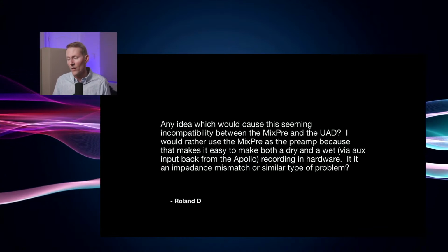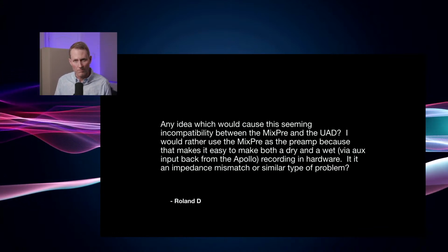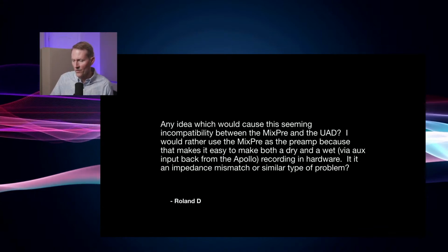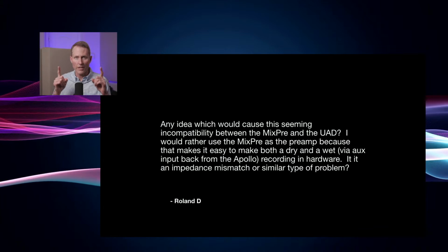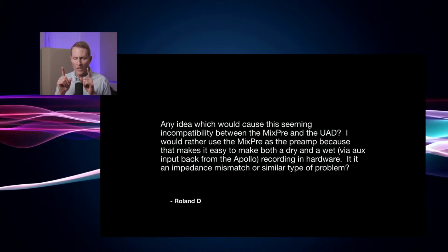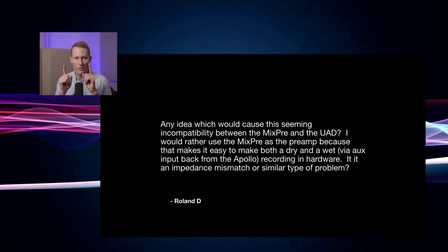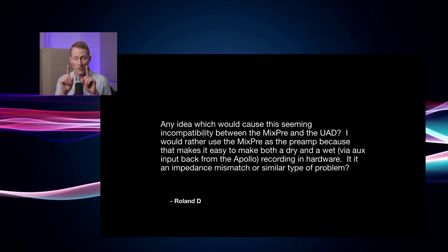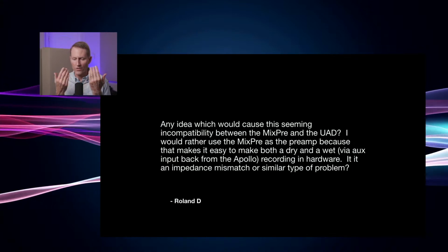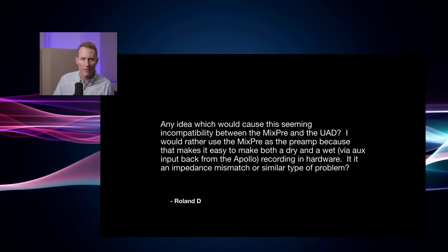The Apollo has a balanced line level input, so that's why you're experiencing that there. So in essence, you're sending a stereo unbalanced connection, and the input is interpreting the two audio channels as the same thing but polarity inversed, and so it's trying to sum them, and that's why you get that thin, tinny sound.